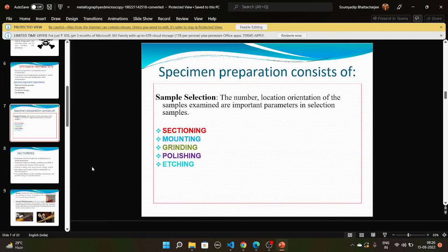Then you go for polishing. Polishing means maybe some polishing wheels, mechanized wheels are there. Over that you can apply silicon carbide or aluminum oxide abrasives depending on the type of the job material, whether the job material is ductile or brittle. So emery paper, then grinding, then polishing is the rough sequence.